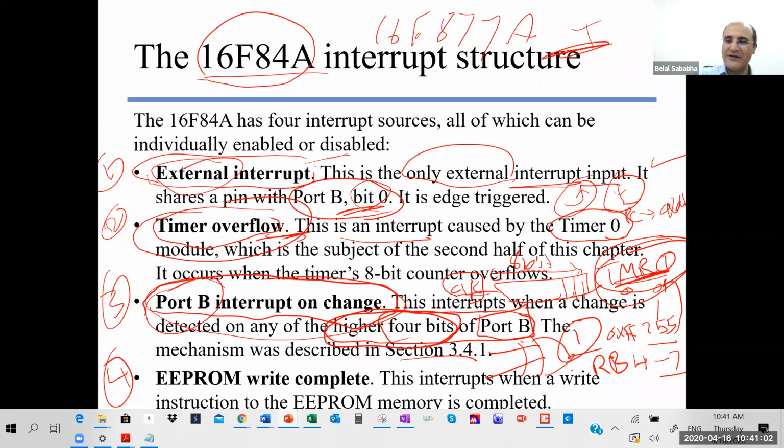Okay? This means that we can tie another four pins to external hardware sources, to a trigger that is pushed when a door is opened, when a window is opened, a contact switch, whatever. But the interrupt will not tell you that pin 4 or 7 has changed.